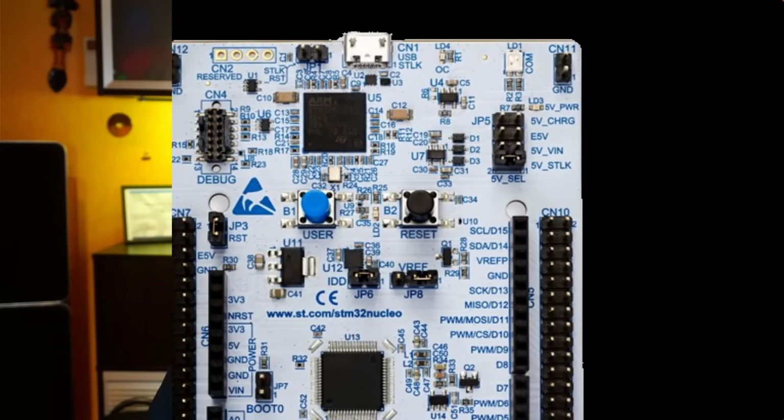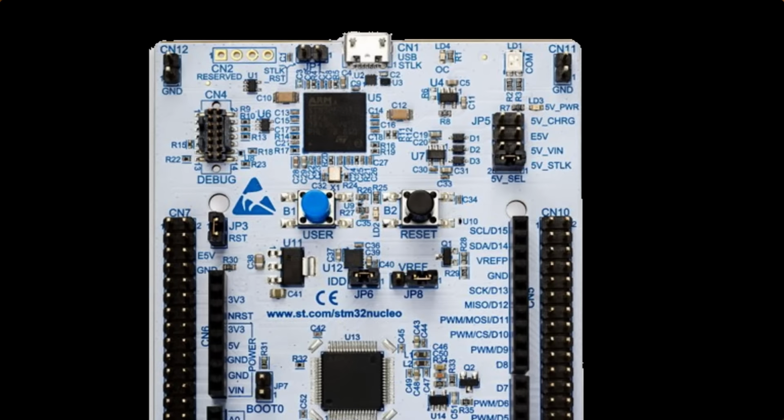In this episode we're going to look into interrupts. External interrupt created from the button that is available on the Nucleo boards. You normally have two buttons on the board, one black that is the reset and one blue that is a user button. You can use that for creating an external interrupt, normally a PC13 external interrupt, and then we also need to look into what callback functions that one triggers and how to use that in our code.